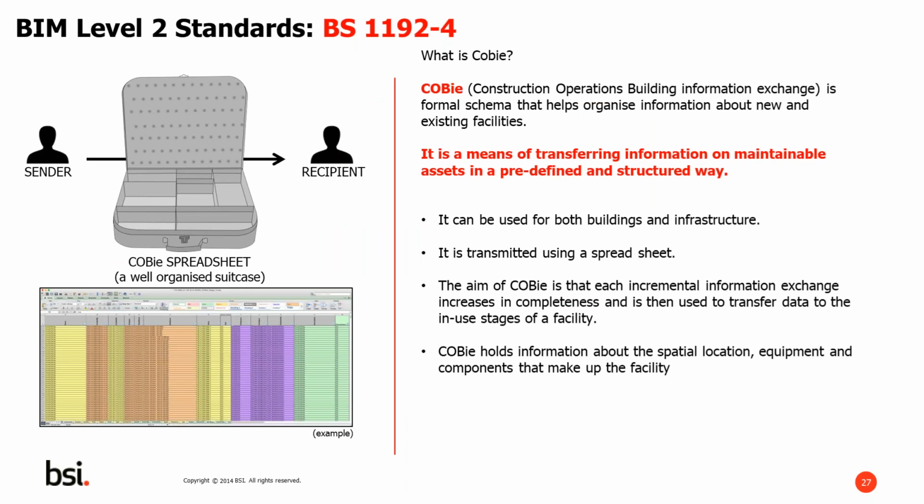Looking at data exchange, BS 1192 Part 4, the COBE document. What is COBE? Construction Operations Building Information and Exchange is a formal schema that helps organize information about new and existing facilities. It effectively is a means of transferring information on maintainable assets in a predefined and structured way.